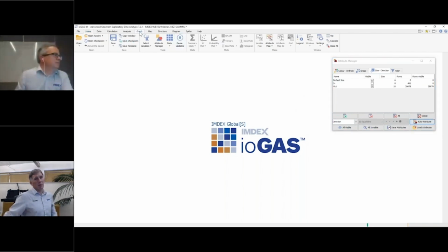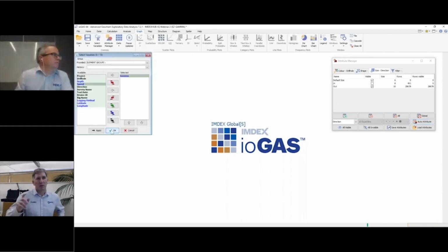Probably worth saying at that point, Fred, in deploying the gamma tool, you can certainly run an in and an out survey, get the driller to run an in and out survey as a way of doing QA. If you're on longer holes, or you're pretty comfortable with the deployment method and you think everything's working pretty well, you can just drop the tool down pretty quick and then pull it out slow, which is probably the best way to do this if you want to cut down the survey time.